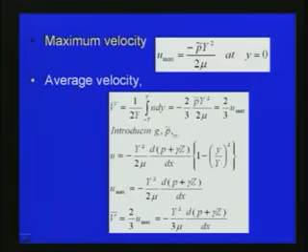If we introduce the terms γ and p bar, which we have already seen, the final expression for velocity is u equal to minus Y² by 2μ d(p plus γz)/dx into 1 minus (y by capital Y) whole squared. The u max can also be written as Y² by 2μ d(p plus γz)/dx, and the average velocity, which we can show is 2/3 of the maximum velocity, is equal to minus Y² by 3μ into d(p plus γz)/dx.